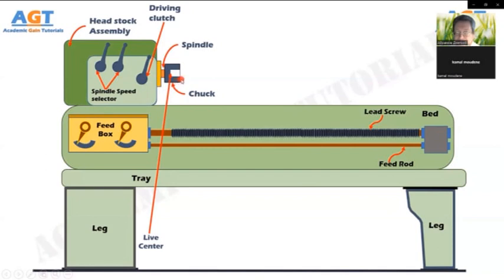Depending on requirements, we usually use two types of chuck, the 3-jaw chuck and the 4-jaw chuck. The 3-jaw chuck is also called a universal chuck because the 3 jaws move simultaneously when any one jaw is adjusted. These 3-jaw chucks are generally used to hold cylindrical jobs. The 4-jaw chuck is also called an independent chuck because in a 4-jaw chuck each stepped jaw is independently operated by a different screw. So, the 4-jaw chucks can also hold square jobs rather than cylindrical.